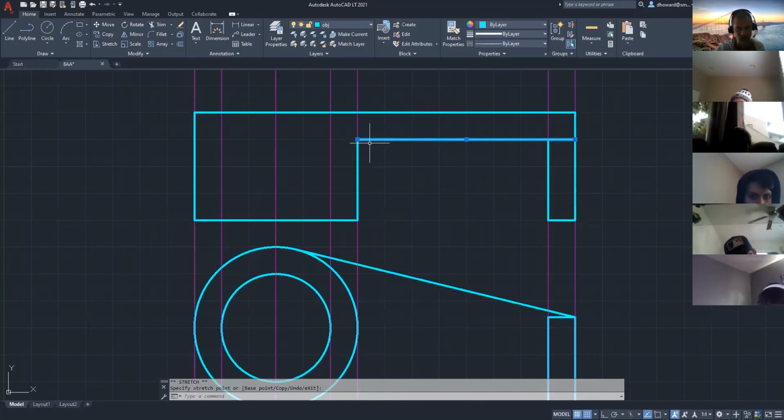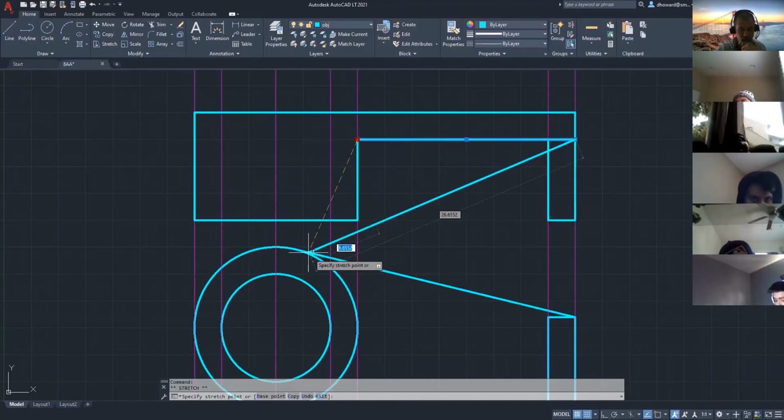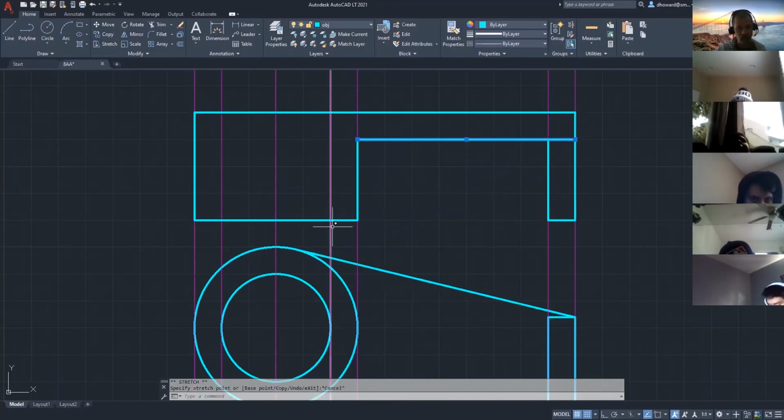This line right here extends back a certain amount. And where it extends back to, as you can see in that top view of the object, is this point of tangency here. So I should have made another construction line, and I'll do that right now, that went from the endpoint of this tangency.